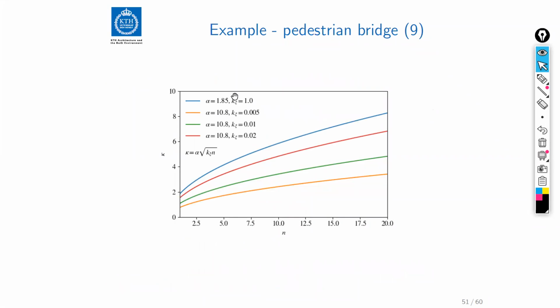and it has caused a few discussions here in Sweden, because if you start considering how pedestrians can synchronize, there is in the literature a model that looks like this. We have an amplification factor that we use to amplify the response for a given bridge, given that one person walks on it. And then we want to extend this to having several persons walking on it. And since we cannot synchronize so well, we need to reduce the total dynamic contribution from this group of pedestrians with respect to their unsynchronized behavior. So this factor does that.